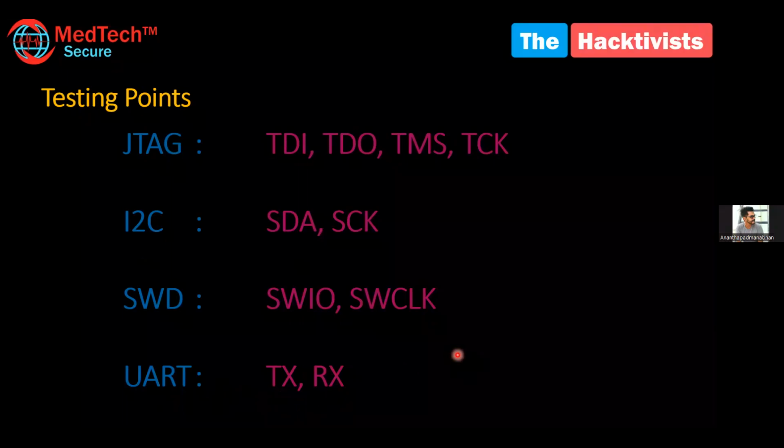And along with this, as I mentioned earlier, ground and voltage are mandatory. It is a kind of default for all these protocols. Regardless of which protocol is being used, we need to find the ground and voltage. So this is regarding the various testing points of the protocols that are used in most of the common IoT devices.